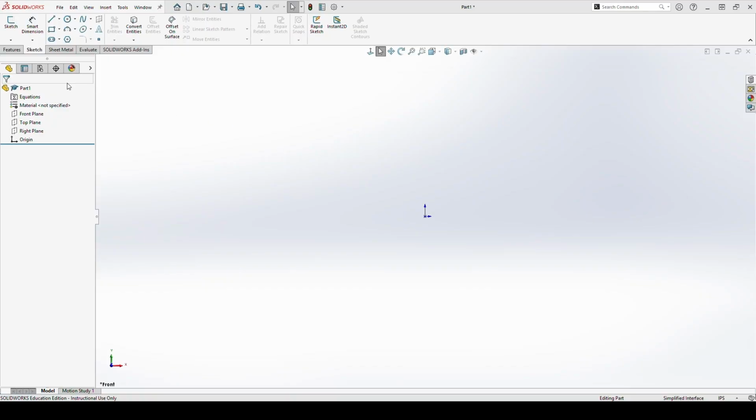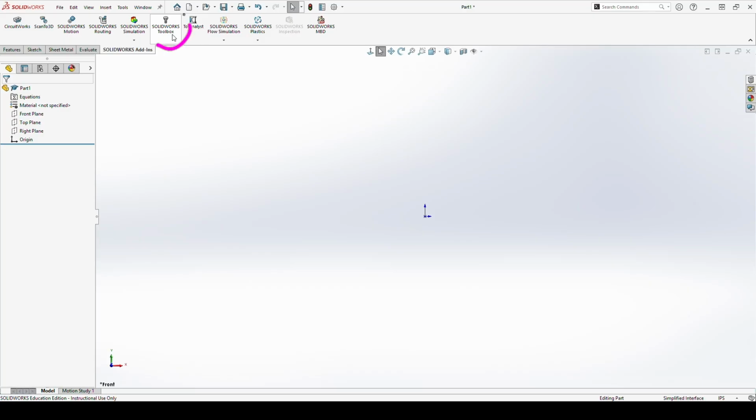With that, SolidWorks Toolbox you can find under the SolidWorks add-ins, and you're going to go ahead and enable the SolidWorks Toolbox right here. And what that's going to do is add a number of add-ins once we load here. And you'll see that a bunch of stuff changed over on this side of the screen. We're specifically after this cam feature right here.